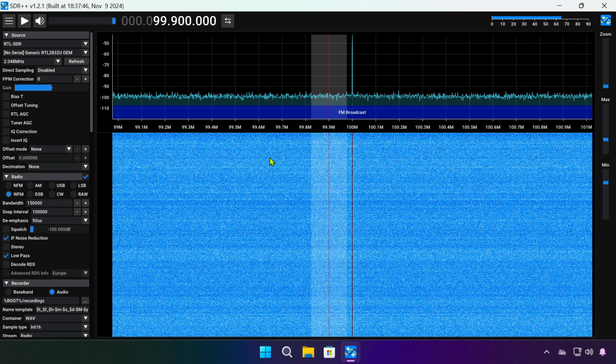So ensure the attached amplifier or antenna is compatible with the receiver's bias T specifications and verify the receiver's bias T provides adequate power for the external device. Using an incompatible setup can damage your SDR receiver or connected equipment.